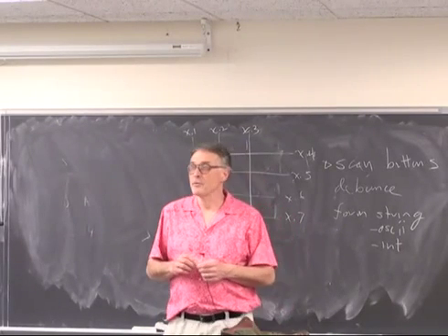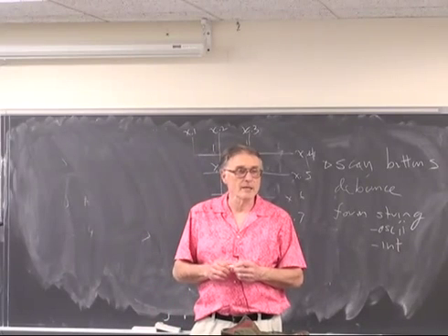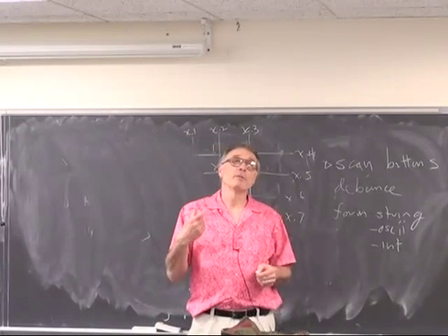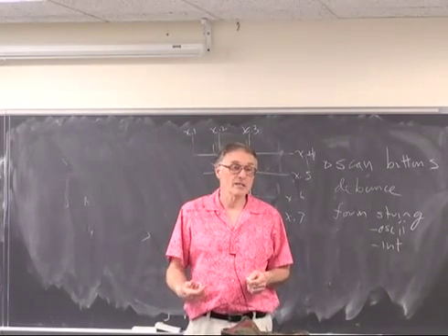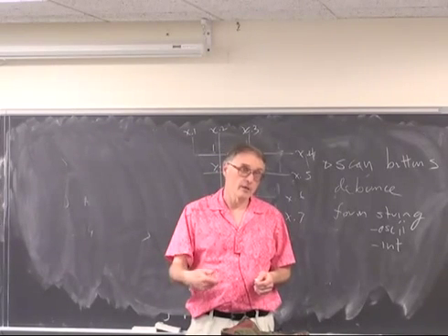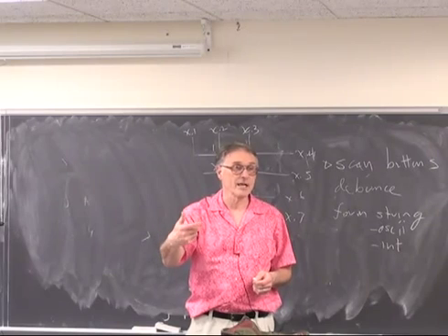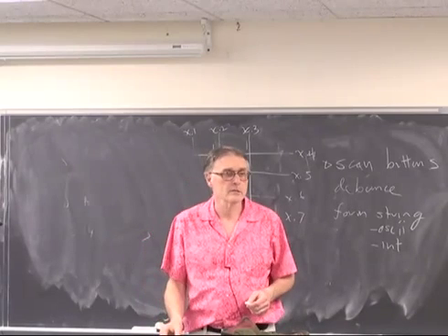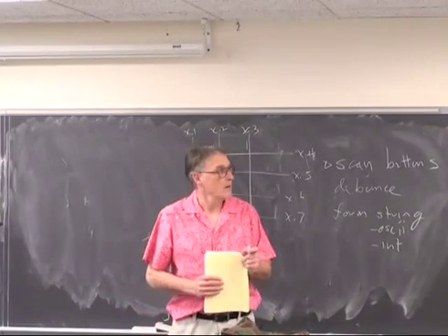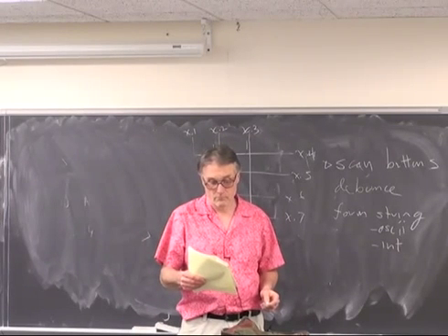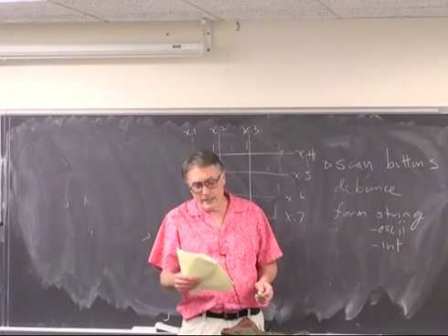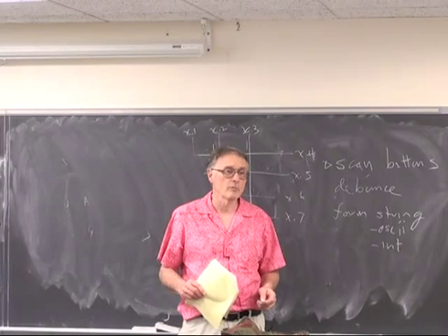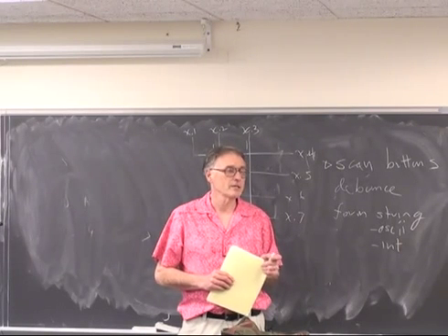There is no lab that requires you to use interrupts on inputs, as long as your code for reading the button is not blocking. You can't spin waiting for the key. You just have to check it, and if it's not valid, fall through and do something else. That may be faster than an interrupt in any case for these simple keypads. Yeah, it eats about 10 microseconds. So it's not a huge kill, but yes, it might be nice to make it interrupt driven.